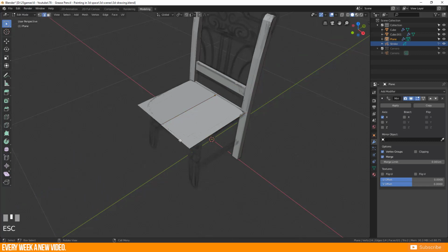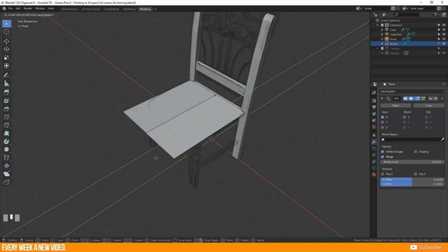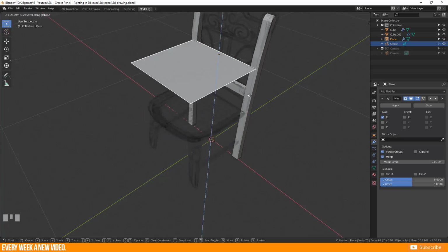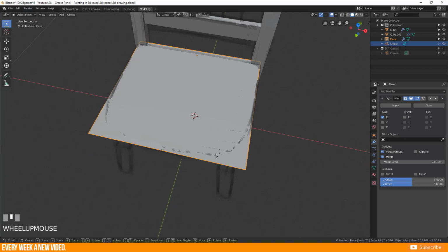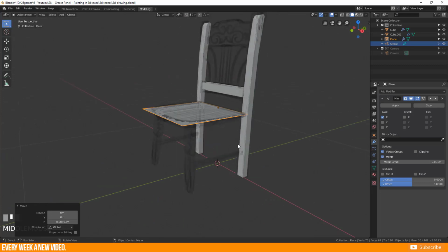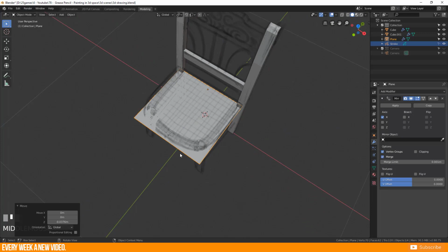And the second shortcut is if you press G for moving, and then the axis X, Y, or Z, then it will move along this axis, for example Y, then it will do the same. Or if you want to move this along the Z axis, then press G and Z. Then it will just move to a higher or lower position here. Well, I want to place it a little bit lower, or probably I will place it much lower first so that I can see the shape of this.